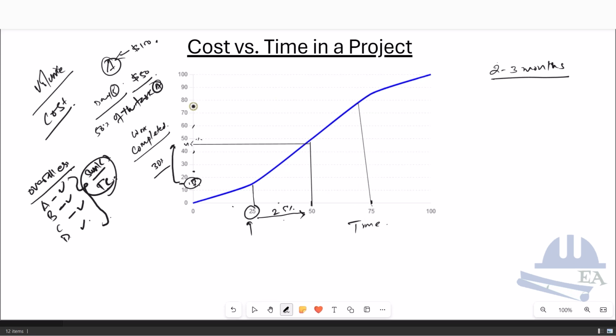So now moving on, at the 75%, what normally happens is that your time and cost both come into synchronization, which means that at normally 75% of the time, the work done is also 70 to 80%. I'll take the average, that is 75%. So at least you have to achieve 70%, and the best you can do is achieve 80% of the work. And even better, you can go as high as 90% of the work, because from 25 to reaching here, that is 75%, it's really good progress.